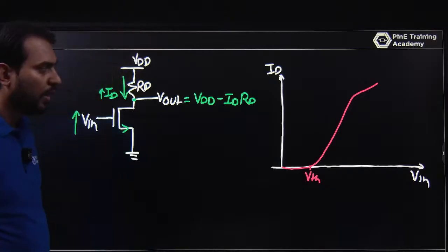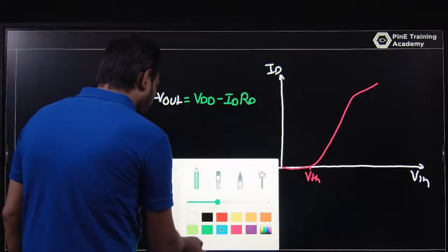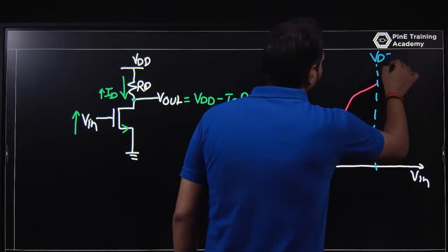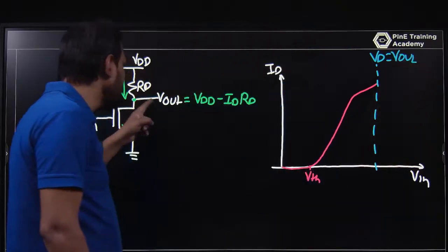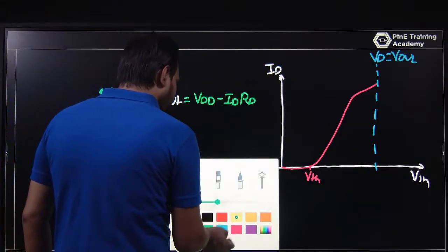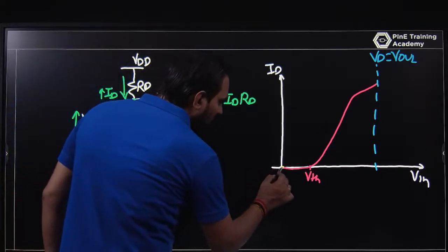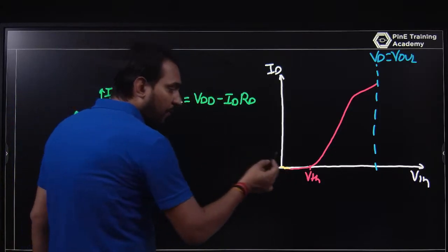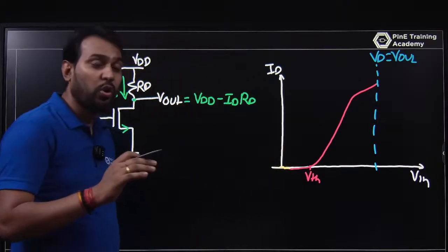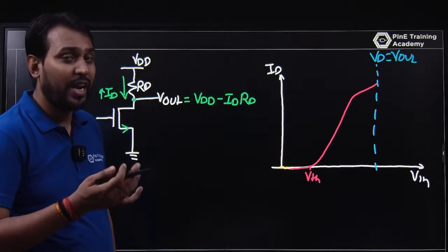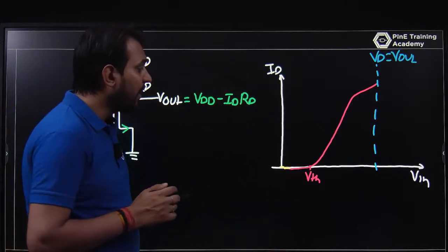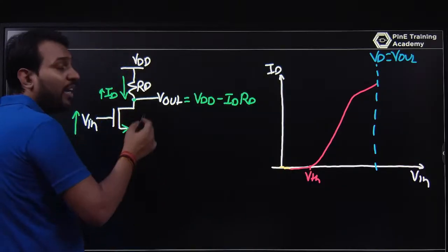and then it will be in the linear region. Okay, if you talk about the drain voltage, or the output voltage, because the drain voltage is your output voltage, what will be the output voltage when the input is 0, or before that VTH? Let the MOSFET be ideal. Before VTH, the ID is nearly 0. In practice, it is nanoampere or picoampere. That current is very small.